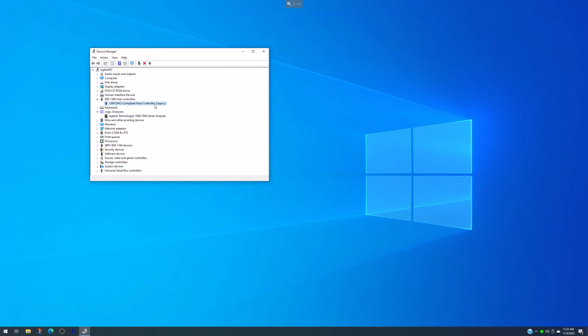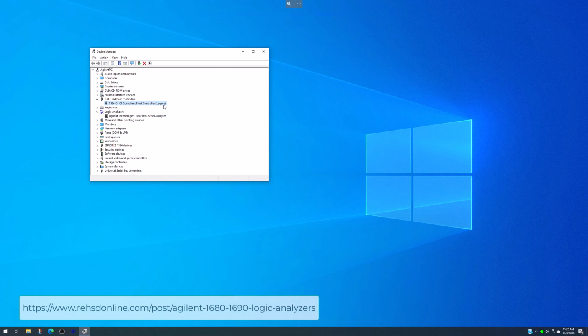And I do have this as a, it says legacy FireWire controller. I have a blog post on this. You can go check out my blog. There's a post specifically for this Agilent type of stuff I'm doing. And I have details on, kind of my setup, but it's basically Windows 10. There's certain FireWire host controllers that I'm finding work, and there are some that don't. And I think that the general trend is that Texas Instruments chipset-based ones are working fine, others are not. So make sure you get a good FireWire controller if you're going to try to have a newer operating system. That seems to be a challenge.